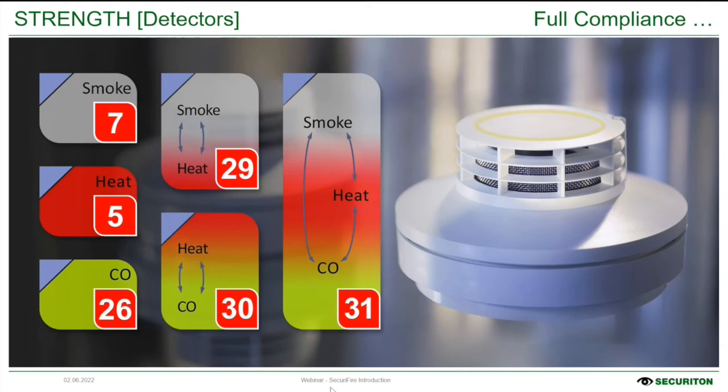Of course, the detectors are fully compliant according to EN regulations. According to EN 54-7 for smoke, EN 54-5 for heat, 54-26 for CO, 54-29 combined for smoke and heat, a 54-30 certification for heat and CO, and the 54-31 certification for smoke, heat, CO.